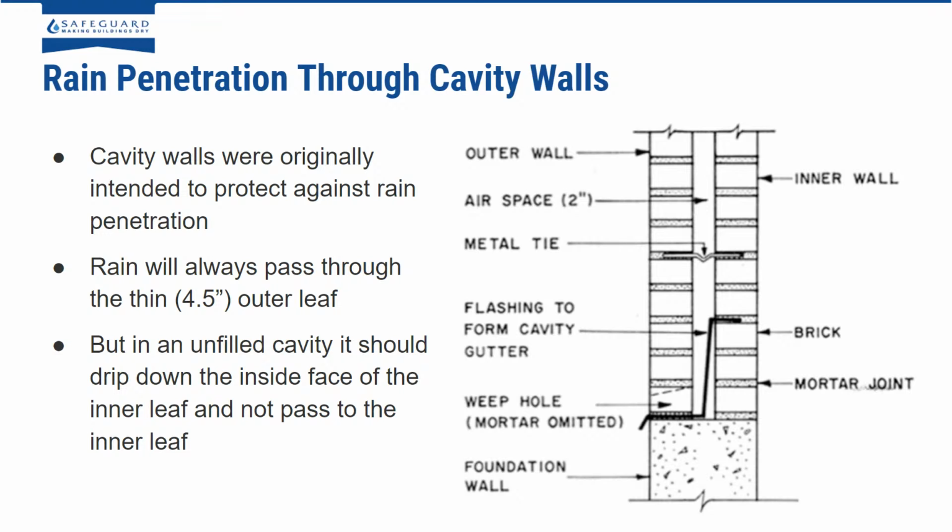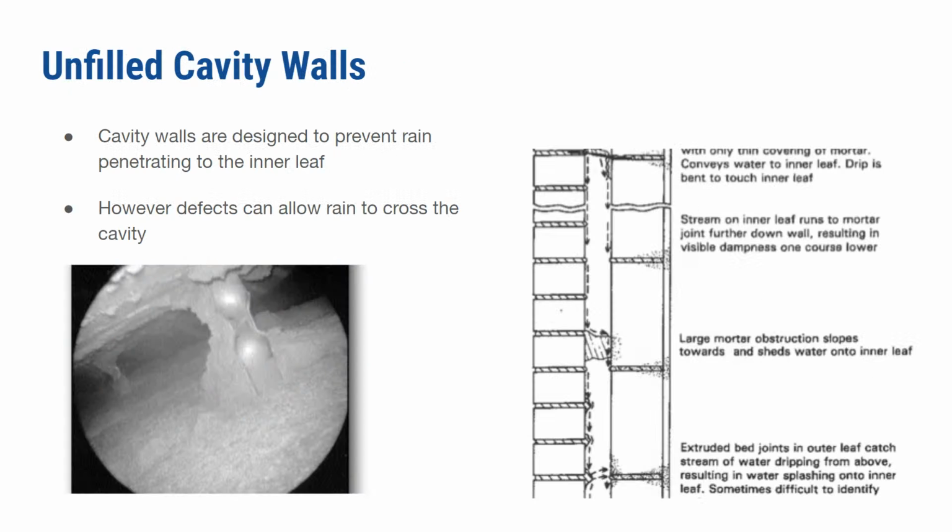And this is fine for unfilled cavities, but can become a problem once the cavity has been filled up. The issue where you can get a problem is where rainwater is allowed to cross the cavity to the inner leaf.